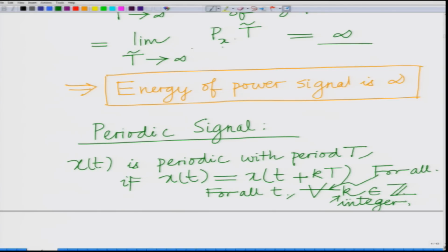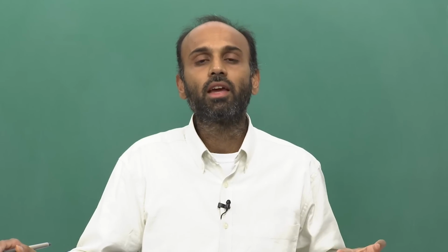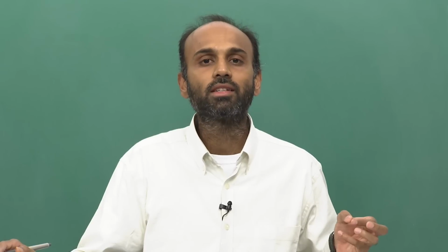That is, we call x(t) a periodic signal with period capital T if x(t) is equal to x(t) plus some integer k times capital T, where capital T is the period, for all times small t and for all integers k.